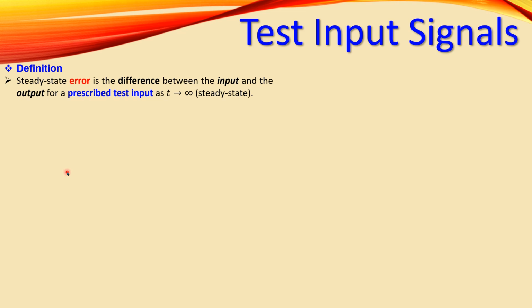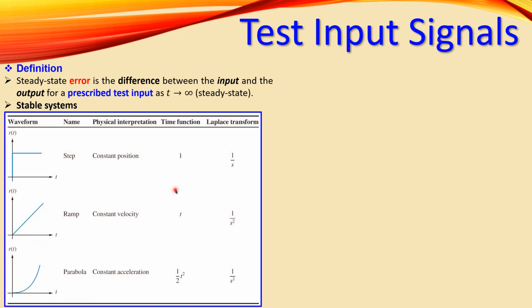And that goes then in steady state for time up to infinity. So this is then mathematically defined in this form. Your system must be stable in order to have a calculation about the steady state error. Otherwise, it is meaningless because the system will then blow up and there's absolutely no constant error in your system response.